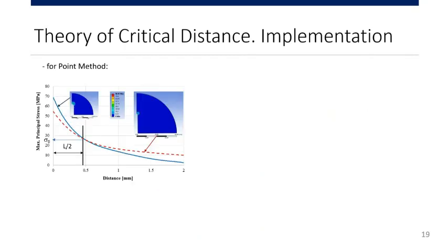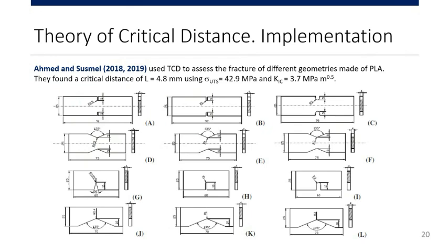We did this. Another method to determine the critical length is to plot the stress variation near the notch or crack for two different geometries with notches. Even one could be in tension, but in this case it's a straight line here. And then from the intersection of these two stress distributions, we can get the critical length and also the inherent stress.